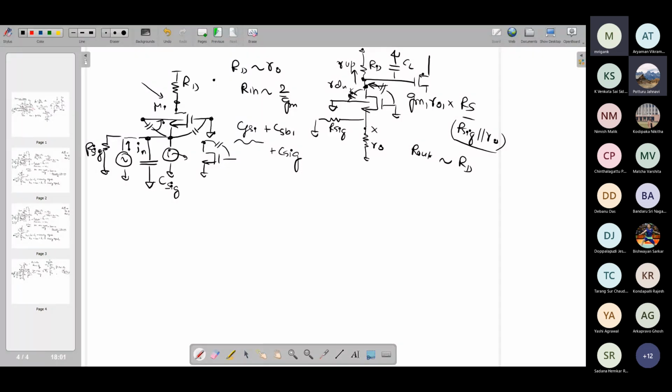If you are given this circuit and you are trying to simulate it, trying to increase the bandwidth, you should be able to understand how changing a parameter, like changing RD or increasing the MOSFET size, affects the bandwidth. Also, looking at the Bode plot, if AC analysis gives you two poles which are sufficiently separate, you will be able to see clearly that the first pole is over here, after that you get a lower slope, and after the second pole you get a much higher slope.